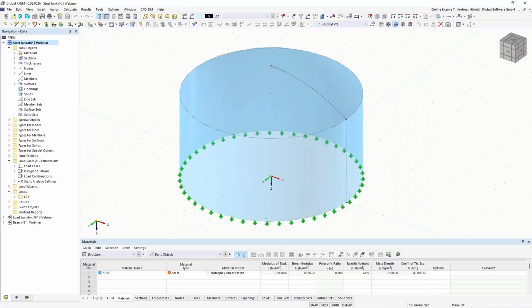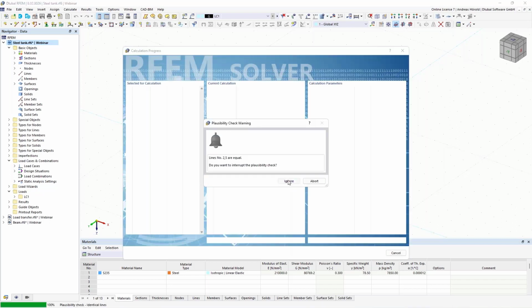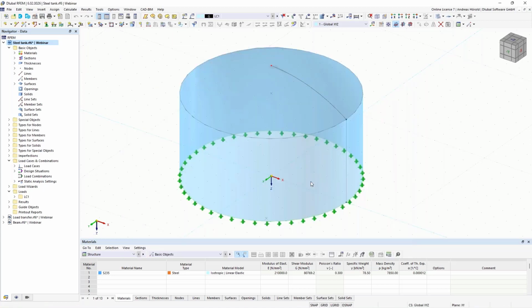We turn to the next question in the program. The next question is, why can't I mesh my model with curved surfaces? Okay, let's try it. We want to create a mesh, and we get this error message: it's currently not possible to mesh a quadrangle area on the 360-degree circle. We are working on a solution, and in the meantime, you need to use a workaround. The surface must be divided into several quadrangle surfaces. I will show you how to do that.